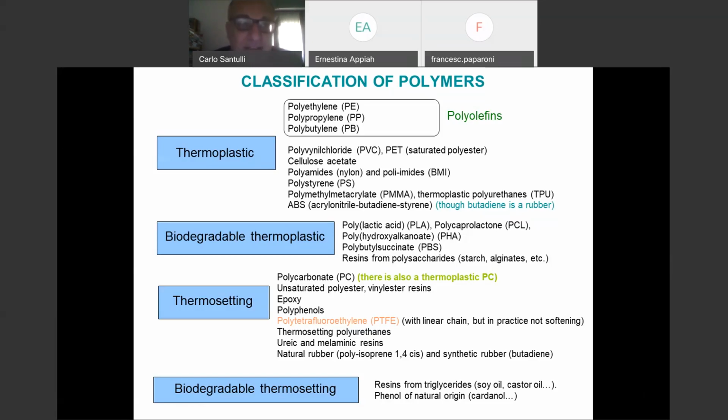One difference which we need to be aware of is that, apart from thermoplastic and thermosetting, there are glassy polymers and rubbery polymers, which have different properties. In very general terms, glassy polymers elongate less. Rubbery polymers elongate more, but with glassy polymers you are able to make sheets. With rubbery polymers, you can make films, but sheets of vitreous aspect are out of your possibilities.